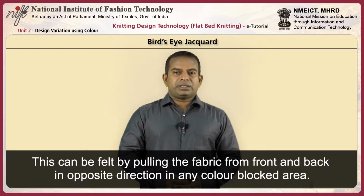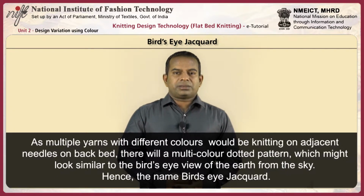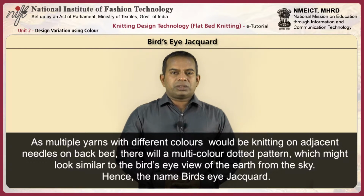Since all needles at the back side will have some color yarn knitted on it, the floats would be concealed between the front and back knit. As multiple yarns with different colors would be knitting on adjacent needles on the bed, there will be a multicolored dotted pattern which might look similar to a bird's eye view of earth from the sky. Hence the name bird's eye jacquard.